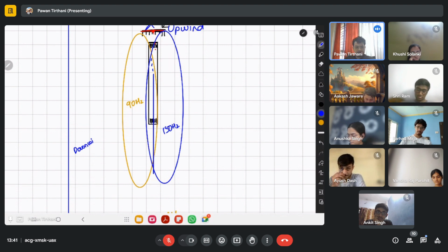So it's different. Now, these radio waves are two overlapping waves, two overlapping sectors. The 90 hertz one is called the yellow sector. It's just a color convention for the purpose of diagrams. And the right one, 150 hertz, is also called the blue sector. Okay, how does it work?